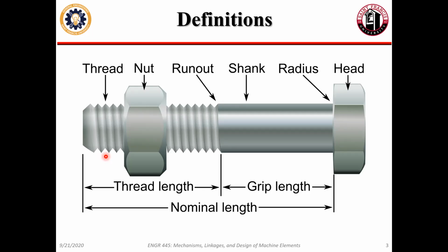Important things to note when you're getting a screw are the length. It's kind of a big deal. Note that this is always measured from underneath the head, so from the base of the head to the tip of the screw. The thing that determines the thickness of the head is, well, not to be weird, but the thickness of the head. So the head type determines how thick that head is.